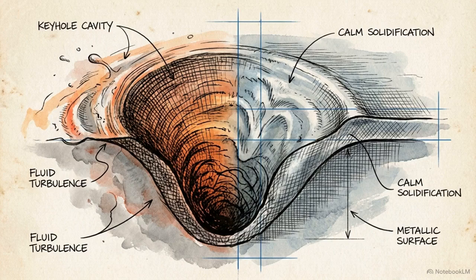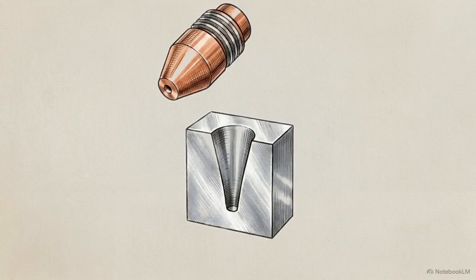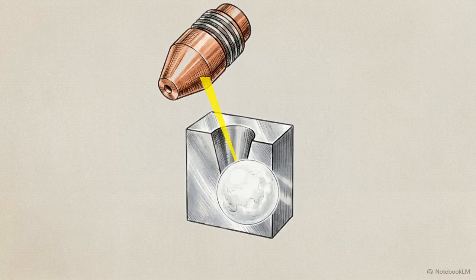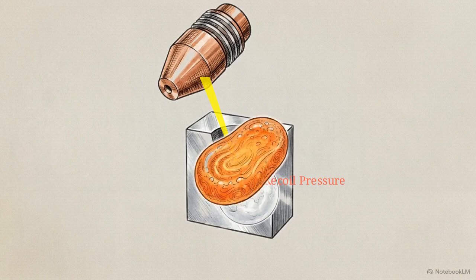microscopic melt pool. When the 1064 nanometer laser strikes the surface, it forces the metal beyond its melting phase, straight into vaporization. This phase change generates a localized pocket of expanding gas, creating extreme recoil pressure driving down into the cavity. That pressure triggers a specific cycle of fluid dynamics. The liquefied material is forced to slide down the front wall of the keyhole, where the recoil pressure then catches it and accelerates it rapidly up the inclined rear wall, working directly against gravity.